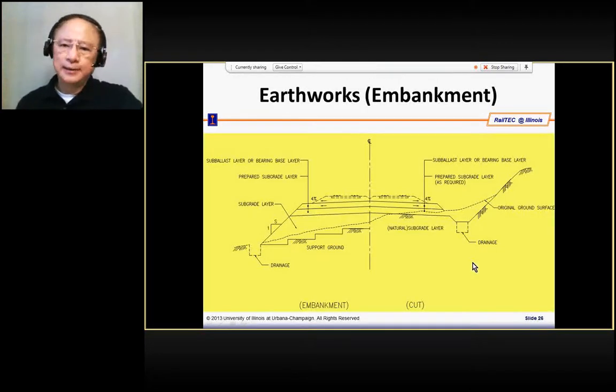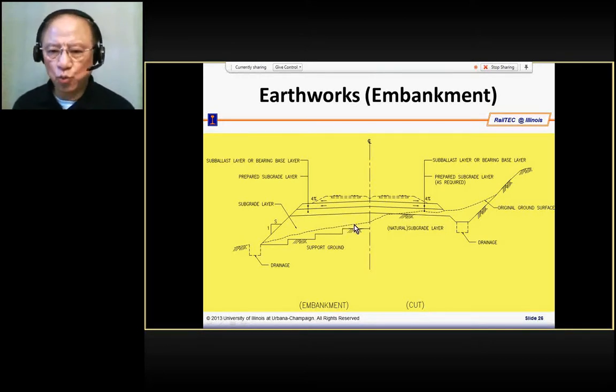Okay, the construction of the earth structure mainly depends on the quality of the construction details. Like this contact surface has to be very clean, and it has to be very well compacted, or basically you have to compact it and you have to cut it back later on to the firm ground before you can construct the second layer. And you have to do this in good weather.